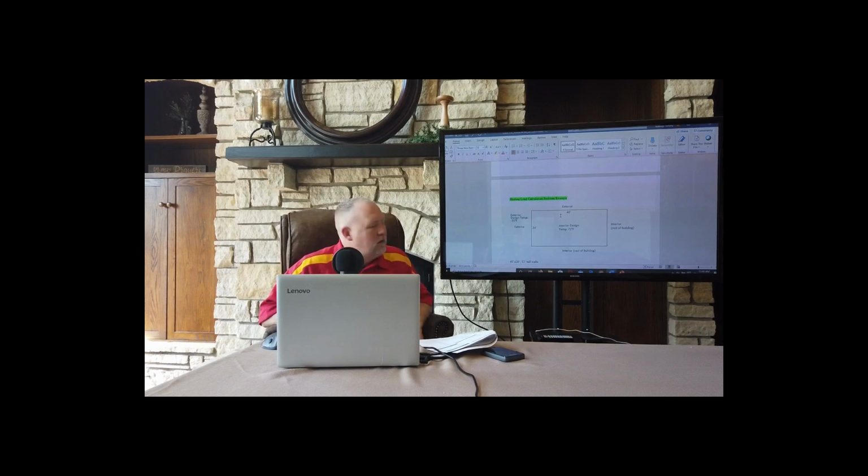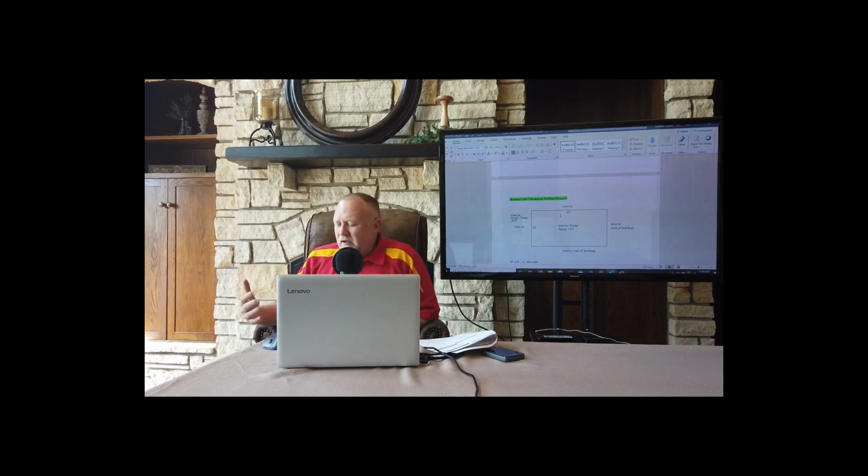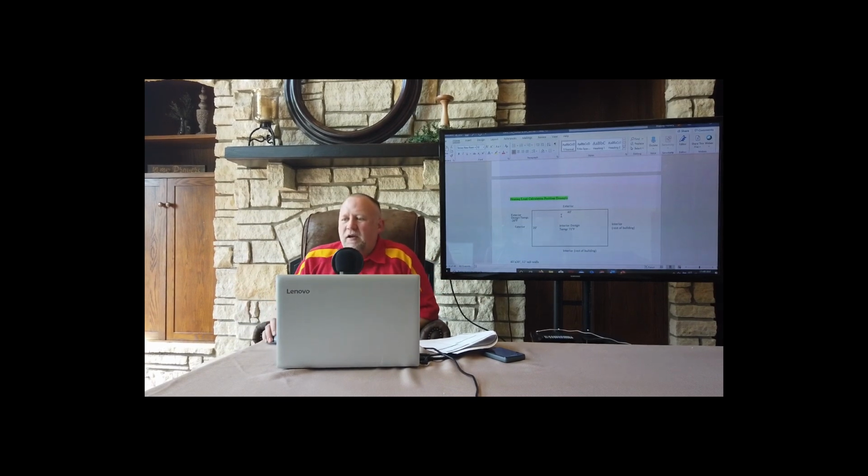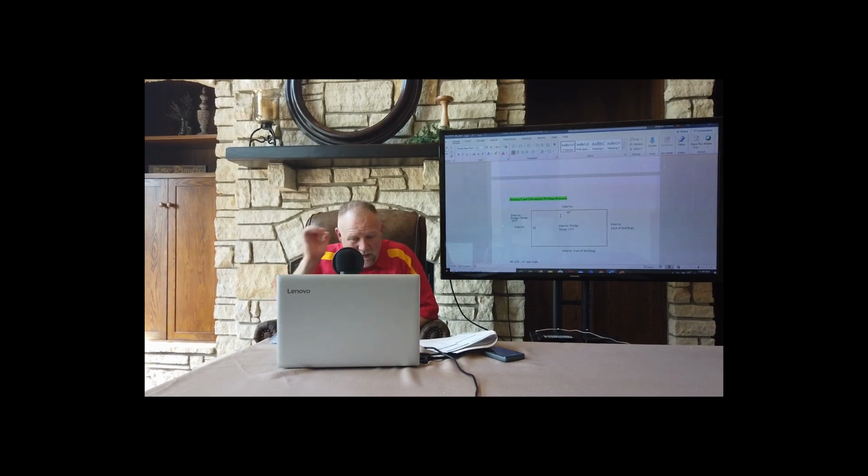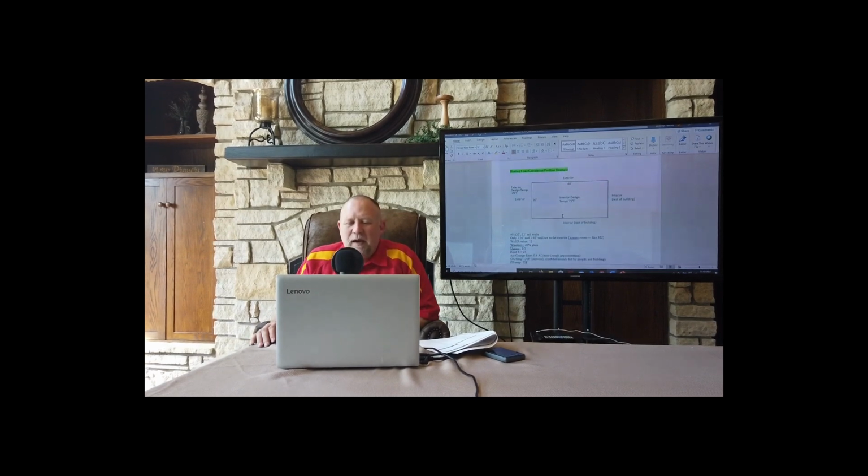Let's do some assumptions. Let's assume the interior design temperature is 72. If I don't say, always use 72, but maybe for an exam or a homework I might change it around to see if you're paying attention. And then the exterior design temperature is minus 20. I like using minus 20. Some engineers might call that a little overly cautious. However, the last few years have shown us that it could easily be minus 20 here in Iowa, and it could be minus 20 for a few days.